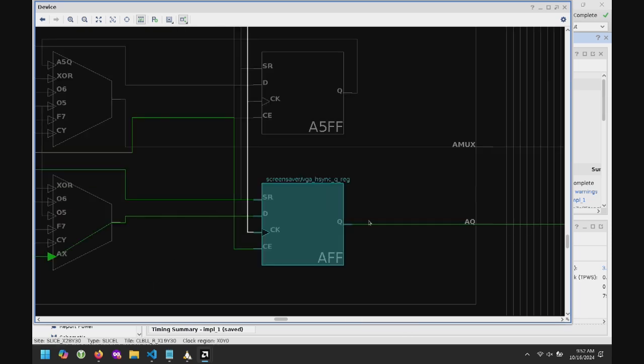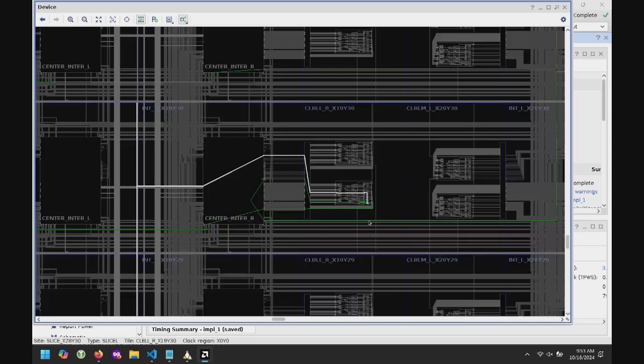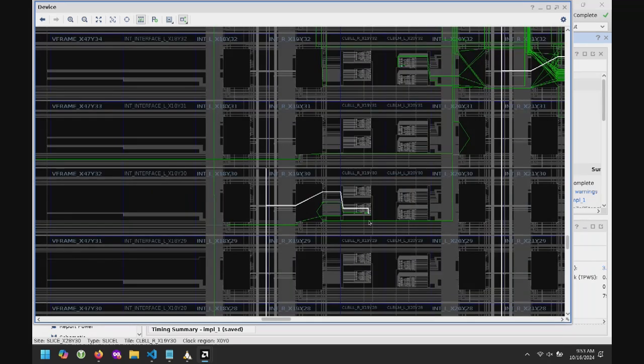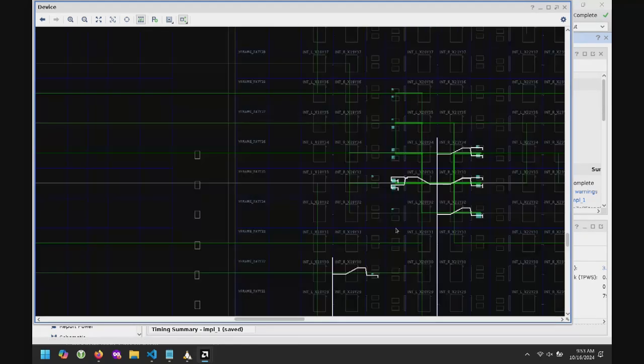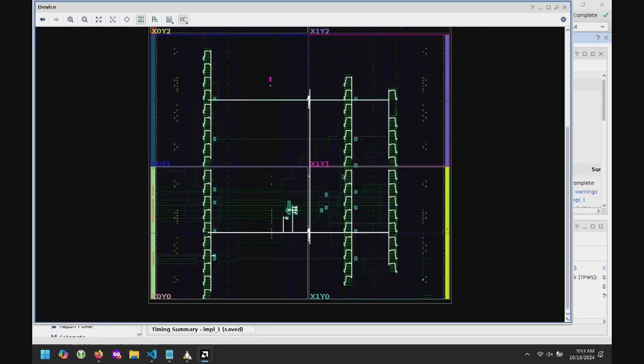So if you wanted to, you could look through this big implementation diagram and look at where all of the different flip-flops and all of the memories and things are generated. So after you've run your Verilog, you can go and see this. But your clock signal, you can see it's spanning all around. And your clock is often the most power-intensive thing in your whole design. Oftentimes, your clock tree can take up upwards of 20 to 30% of your entire power usage on your entire chip.